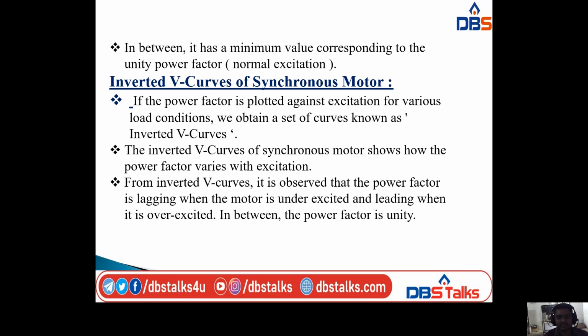Coming to the next concept, that is inverted V curves of synchronous motor. If the power factor is plotted against excitation for various load conditions, we obtain a set of curves known as inverted V curves, that is the reciprocal of V. The inverted V curves of synchronous motor show how the power factor varies with excitation.